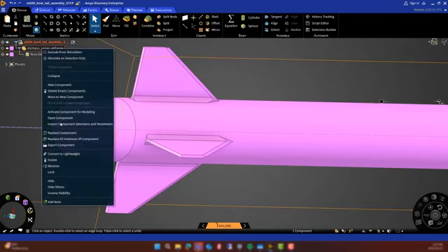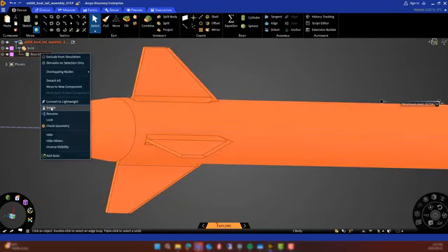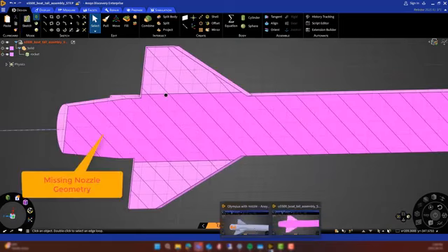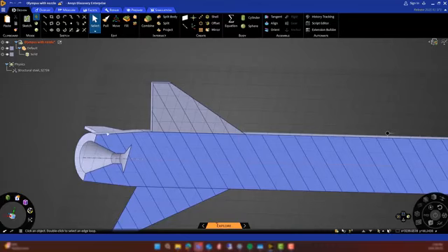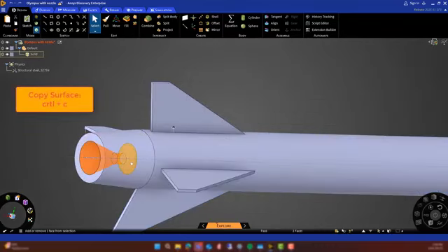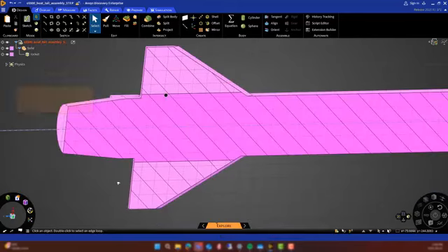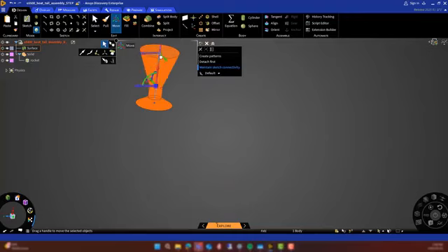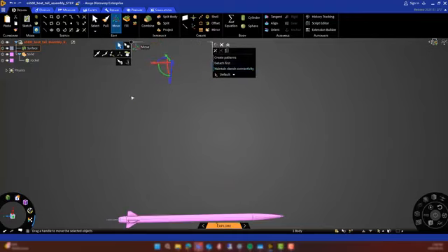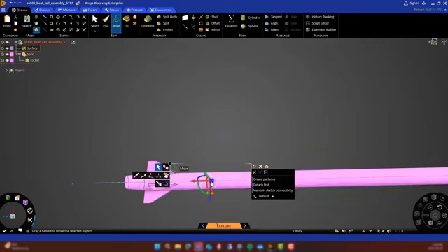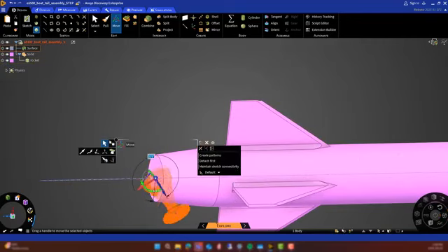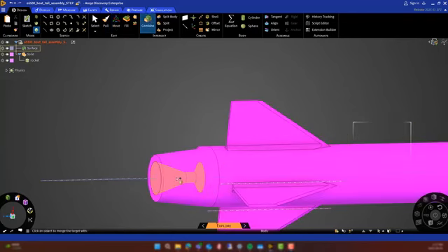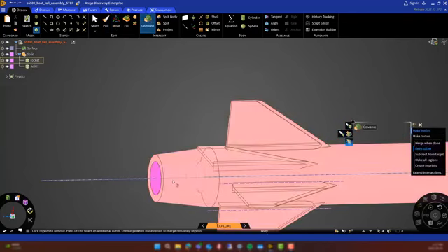And once there's one combined solid object for the rocket body, it can be renamed accordingly in the object tree. And finally, since there's no void space for the nozzle shape, we'll go to the provided complete geometry, copy the nozzle surfaces, and paste them into our working rocket body. The surface representing the nozzle shape might need to be repositioned using the Move tool depending on the model orientation. This surface can then be used to split the solid body and create a void space for the nozzle fluid.